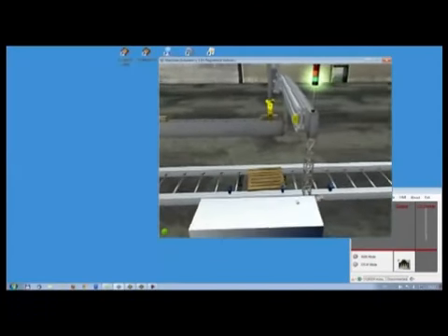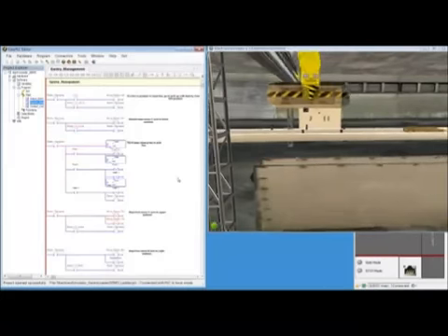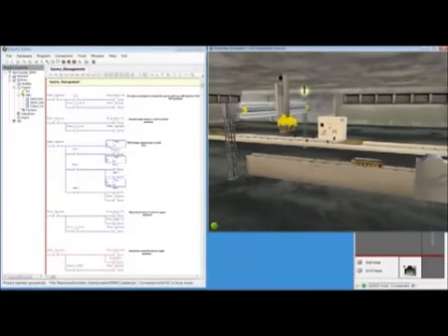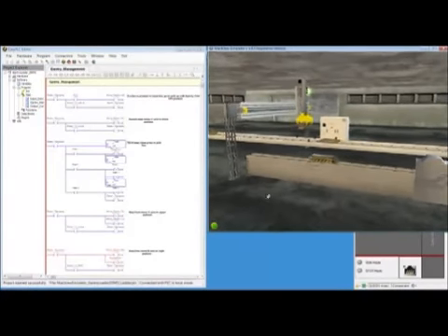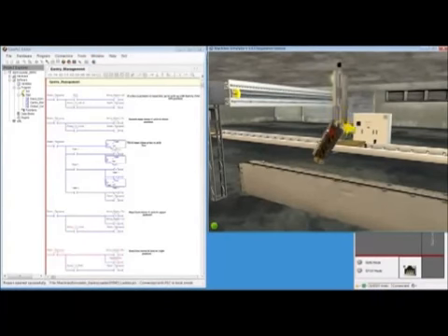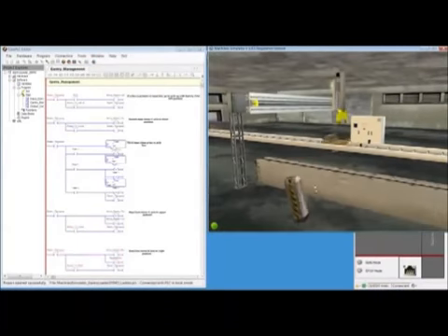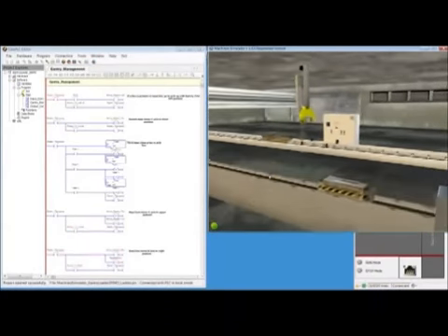You can connect the editor with Virtual PLC CPU in order to test, check or debug your logic programs as if it were a real system. You will see the ladder elements change their color when the inputs or outputs are active. In Machine Simulator, you can interact with the elements to cause errors or malfunctions or to alter the course of the process. Then you can check how stable your program is.